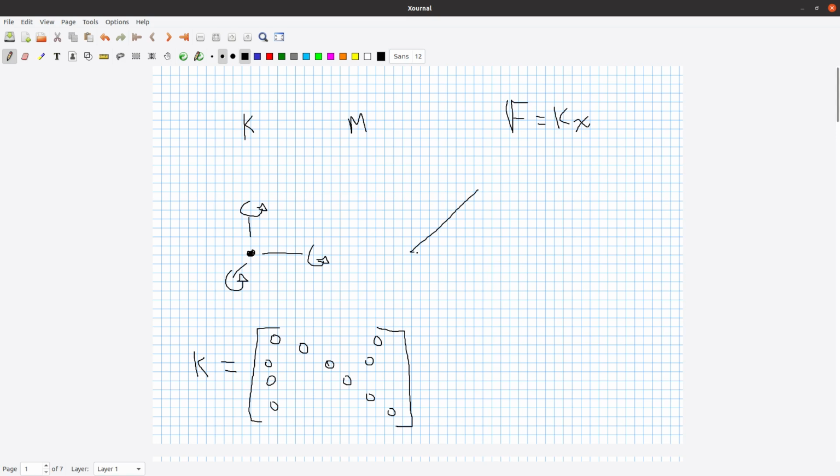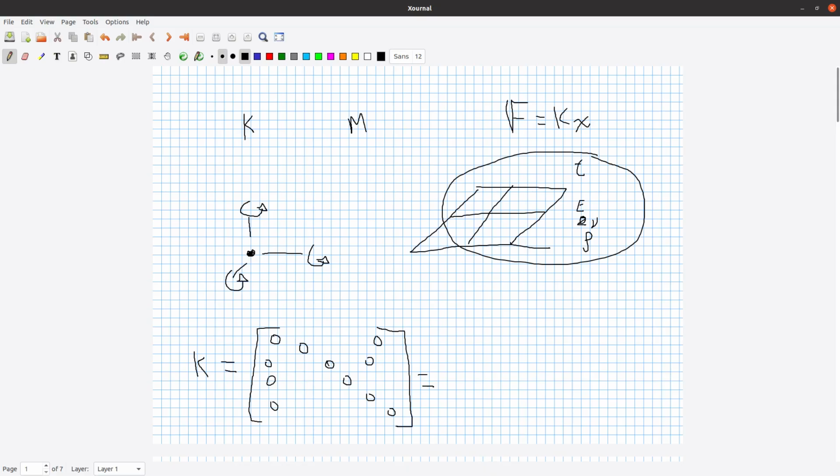We're going to define some elements. So we have something like this. We're going to define a thickness. And then we're going to define some material properties like a Young's modulus and a Poisson's ratio, and then a density. We combine this all together, and then our elements are able to generate stiffness values for the stiffness matrix. So after we do all of this, our stiffness matrix will have non-zero values inside. So something like this here in the bottom right.